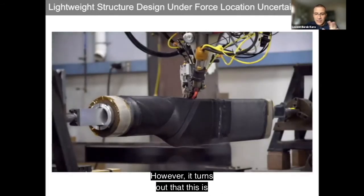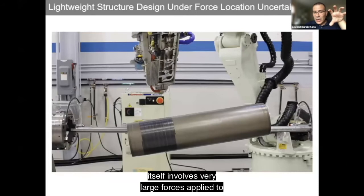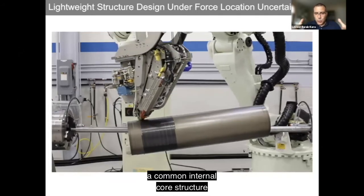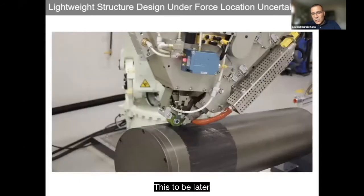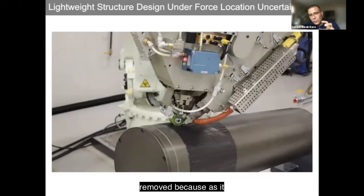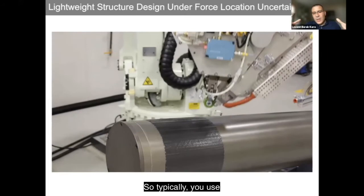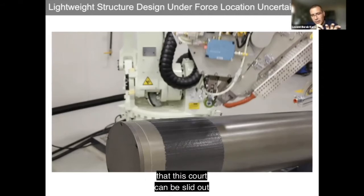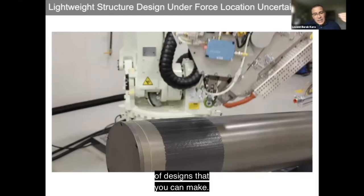However, it turns out that this is a massively complex problem because the manufacturing process itself involves very large forces applied to a common internal core structure, and a geometric limitation: this structure has to be later removed, because as it currently stands, it's a very heavy part of the design. So typically you use a steel core structure and then you put the automated fiber placement on top of it. However, the one requirement is that this core can be slid out of the final cured skin, which limits the types of designs that you can make.